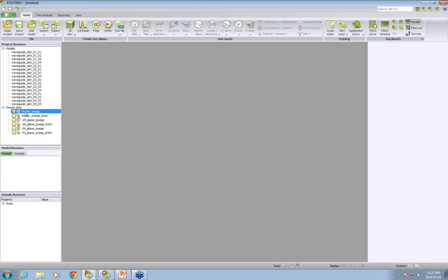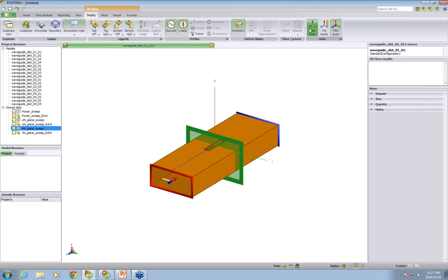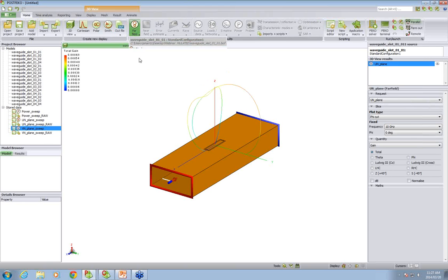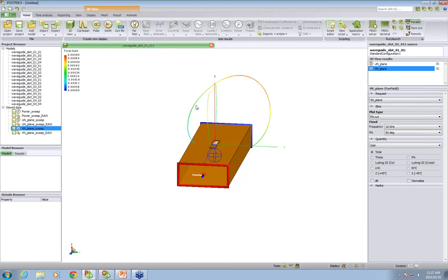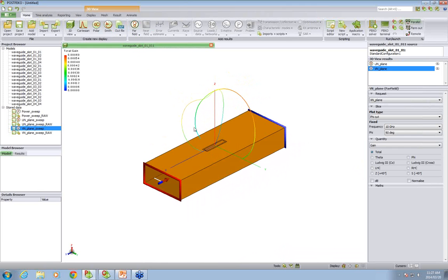Okay, so you can see that it found a power block and 2 far field blocks. So if you look at the original model, this is just one of the permutations. We have far field pattern simulated in the co and the cross polarization axes, and each of these models contain a different slot value, slot offset and slot length.